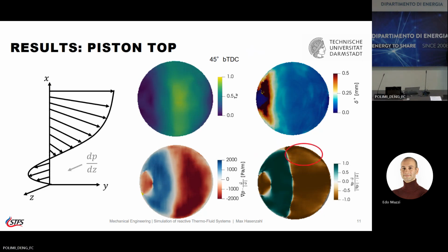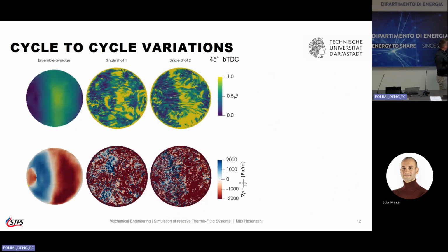And what this points to is that you have some transversal forcing, pressure gradient forcing, and this can lead to boundary layers which skew, and from what I read, they tend to skew faster in the lower part because you have lower momentum. This is also something that's quite complex, obviously, and if you, for example, do model development, we would have to take this into account as well.